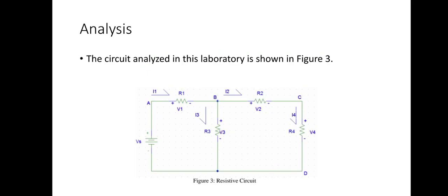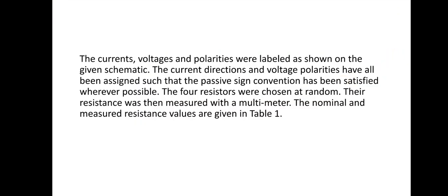The passive sign convention with respect to KVL can also be applied to KCL. On many schematics, polarities of resistors are already assigned, so the direction of the current should be assigned such that the current is entering the positive terminal. This will simplify later calculations.